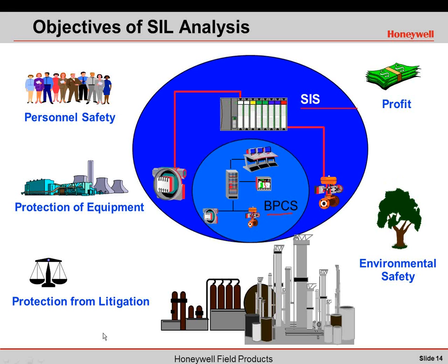On a P&ID, is the difference between a high alarm and a high-high alarm that between the BPCS and the SIS system? No, the high alarm and high-high alarm are actually all part of the basic process control system. When you get to the high-high alarm level, if everything is working right, it should shut the system down.